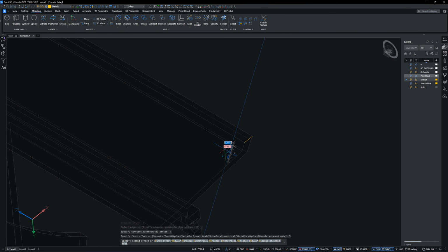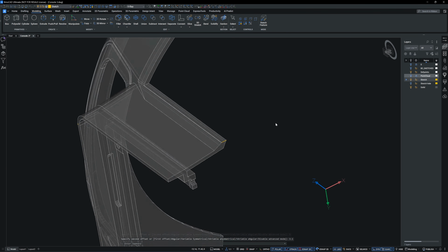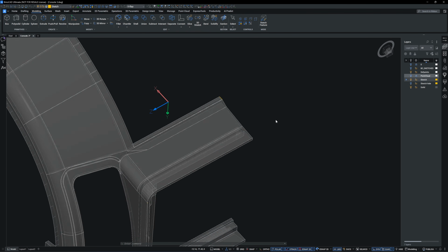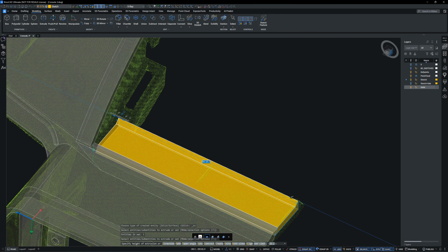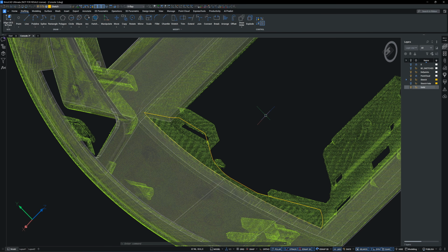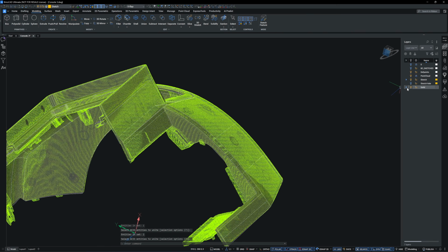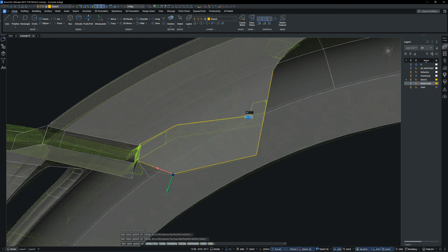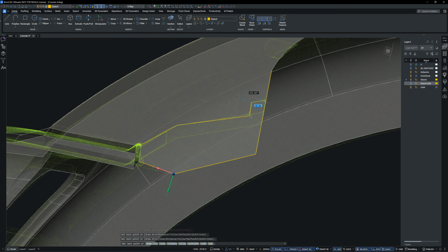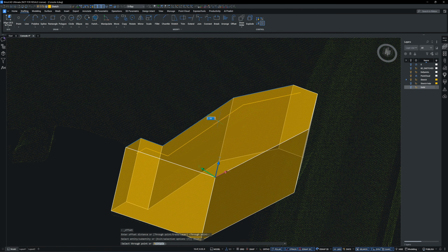Next, I use the unequal length chamfer to adjust the surface shape here. And here I add one small extrusion. And here I extrude the vertical wall for the glove box. From this point onward, the modeling becomes easy. Just a few sketches combined with the push-pull command.